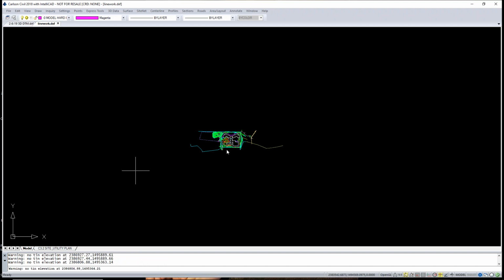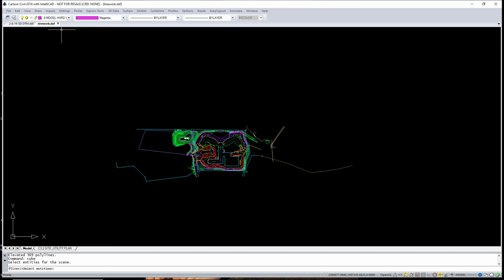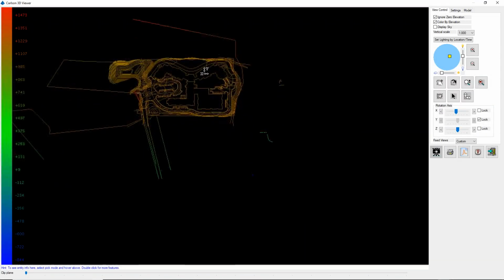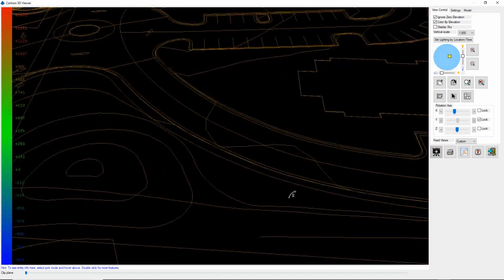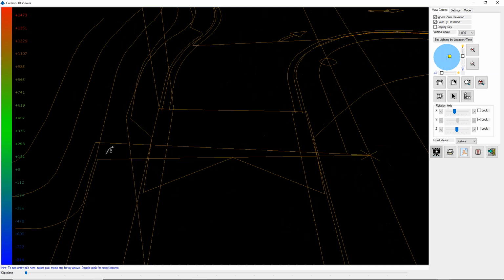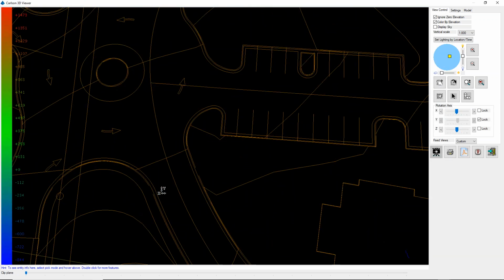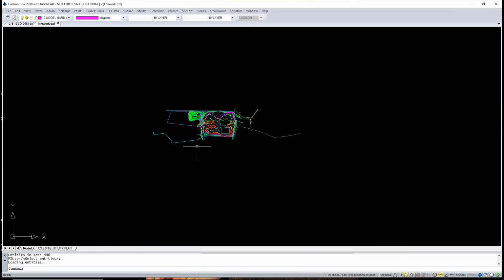You might not have to do this because I imagine your lines were probably 3D and you probably flattened them because a lot of the other data collectors, Trimble, Topcon, all of them, a lot of the old ones couldn't handle 3D line work either. So now we should have 3D line work. I know on this job they are using the Icon Rover, so they can do everything in full 3D. So now the only places that are going down to 0 are outside of the surface model area anyway, or something weird going on. But for the most part, this is going to be fine. As long as all the curb and everything is right, since they're actually going to be staking that, not the boundaries and all. So we can close that out.